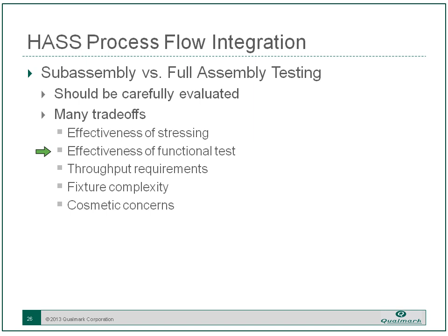If I cannot fully functionally test a sub-assembly unless it is connected to another assembly that has to be 2 inches away from it, then I can't do that. But maybe it does make sense to take lots of some sub-assemblies and do them as lots, and then look at the full-up assembly, and maybe you don't even need to do HASS at that full-up level. Or maybe there's a reduced stress HASS that you do at that full-up level. Think about it. There's not a fixed statement to be said about this. It involves trade-offs and needs to be thought about for your unit.